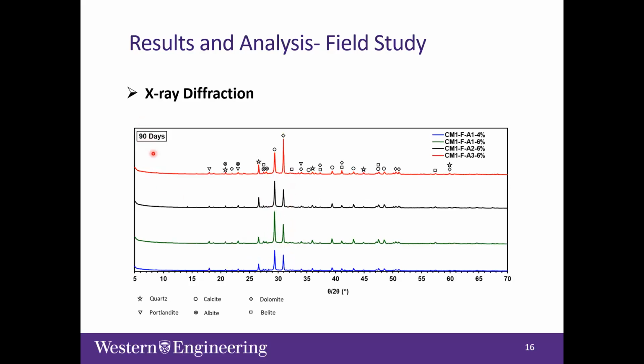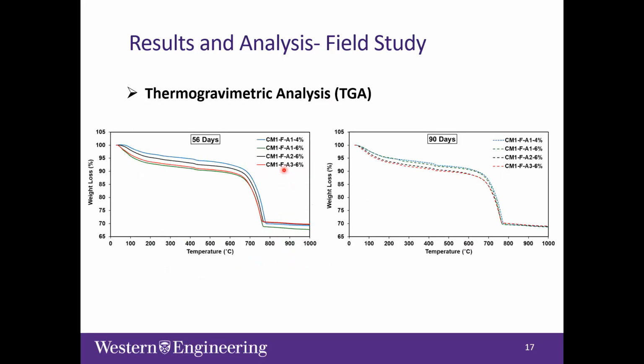And from 56 to 90 days, we'll even see no significant difference. So the XRD data didn't explain much of what happened in the compressive strength behavior, because we expected a significant hydration product given the significant increase in the compressive strength, but this is not the case here. Even having the TGA results, we see that there's no significant weight loss between the different mixes.